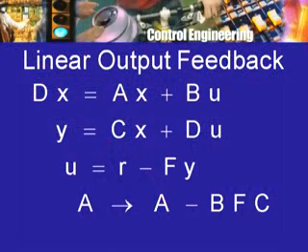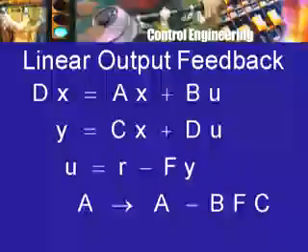Of course, what I have illustrated is only for linear time invariant systems. Differential equation is linear time invariant, the output equation is linear time invariant. Therefore, matrix, eigenvalues, characteristic equation, eigenvalue problem, all these are tools which can be used. The moment the differential equations become nonlinear, the output equation becomes nonlinear, then the situation is much more difficult, and there are no generally applicable tools that are available even today.